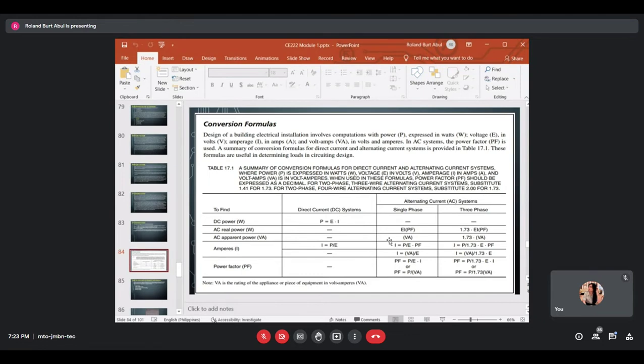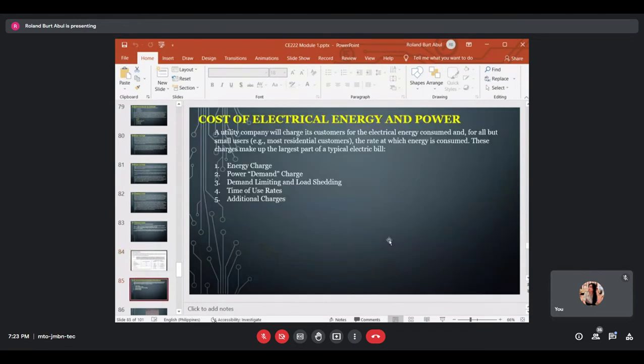So there are three advantages of power factor correction. First, a high power factor reduces the load currents, resulting in a considerable saving in hardware cost such as conductors, breakers, switchgears, substation transformers, and so on.